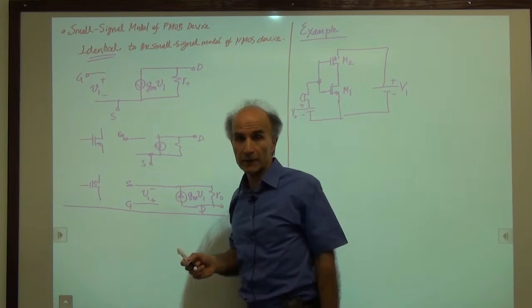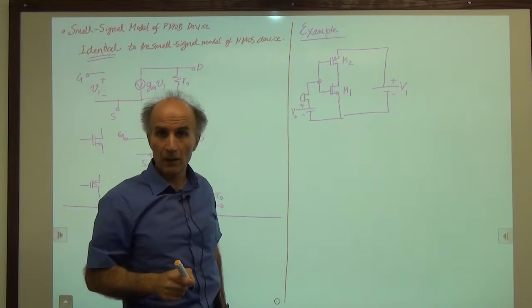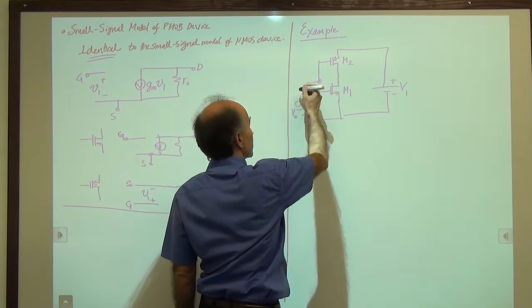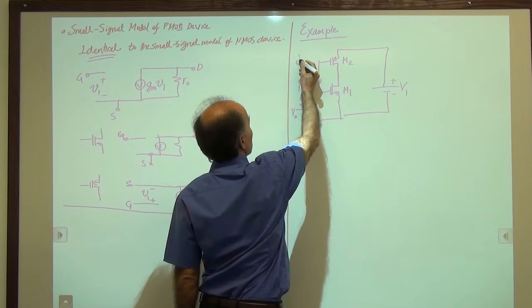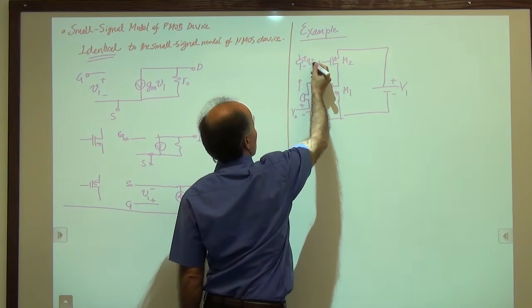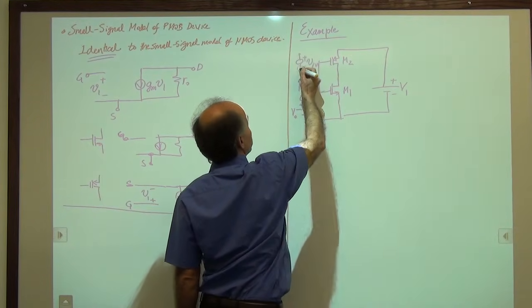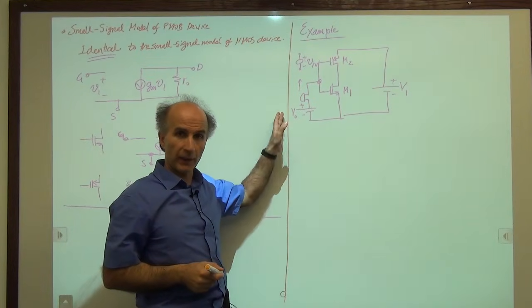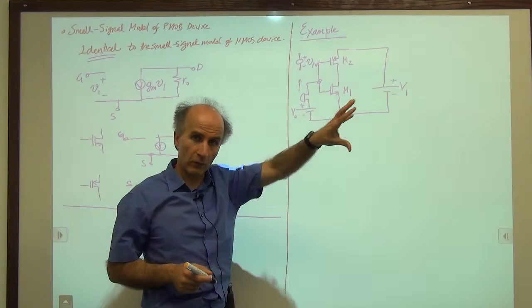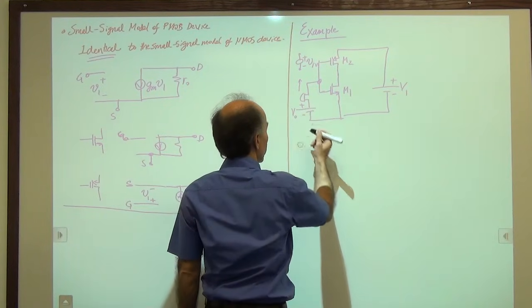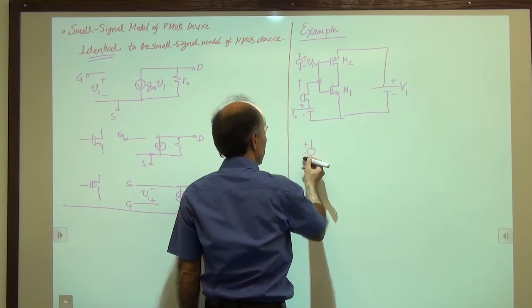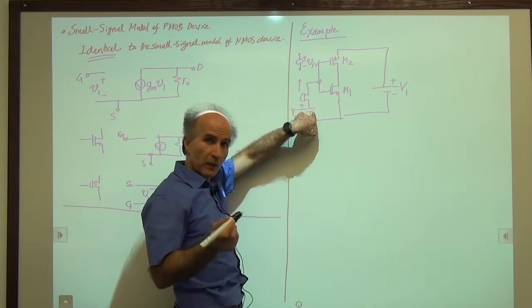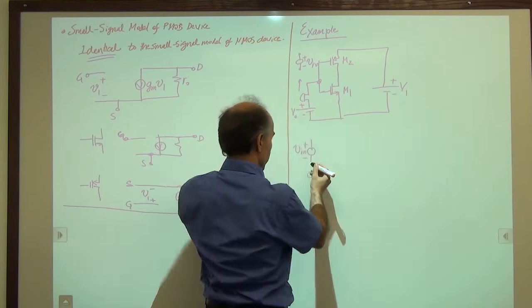And we would like to draw the small signal model of the circuit, including everything, channel length modulation and everything. And we assume that this microphone can be modeled by a simple time-varying voltage source called Vin, like before, right? Okay, so again, we start from the left and replace everything with this small signal model and go forward. So, microphone becomes a voltage source, very good. The battery doesn't change with time, becomes a 0 voltage source, so a short circuit.